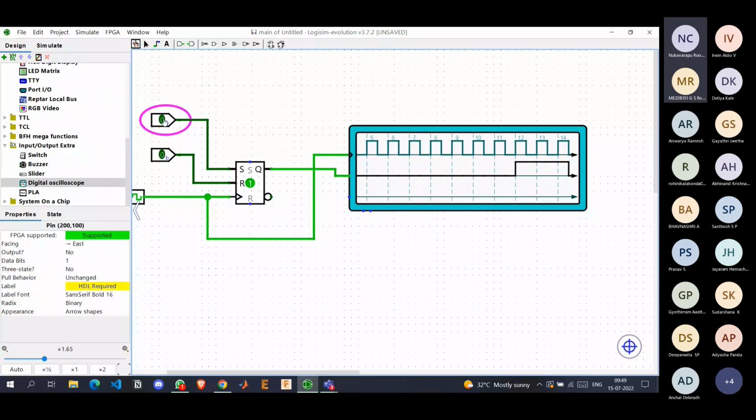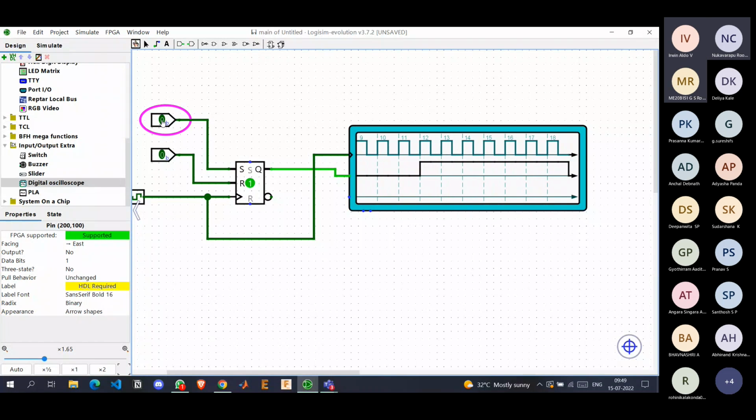I take my finger off the button, and now the value will be 1. The value remains 1 because we again put the inputs to 0, like pressing it and leaving it means it goes back to 0. So it is in the memory state, and the value of Q remains 1 as long as we keep the inputs at 0.